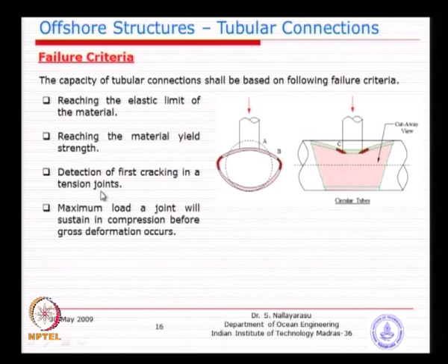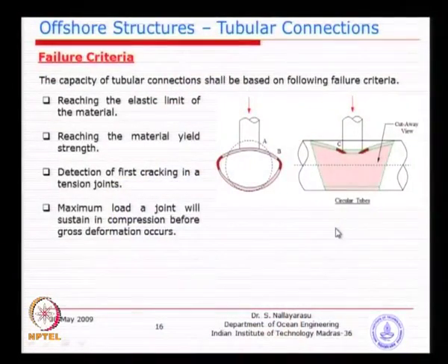and material yield, and then the first cracking and the load at which it occurs, which is what we saw in that. So we need to have a test or FEM simulation run until this. You can't do a finite element analysis in the elastic state and take the result and use it, which is not correct. We need to do a finite element analysis until the failure occurs and then note down the capacity until first crack. So substantial computational power is required. Normally, if you do a static analysis, it may be faster, but when you want to do this kind of elastoplastic analysis, it may take longer.